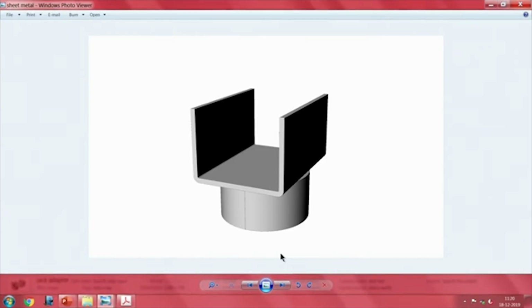So, I will take a break of this whole session here at this point, so that you will try to see how well variations and production also have to be incorporated into your designs. While solid modeling is convenient, I can make a very impressive looking thing. One way of dealing with it is probably make two of these parts, one at the extreme upper end of the tolerance, another at the lower end of the tolerance, and see whether they will fit each other by manually trying to show them on your screen. That will only clarify your concepts for you.